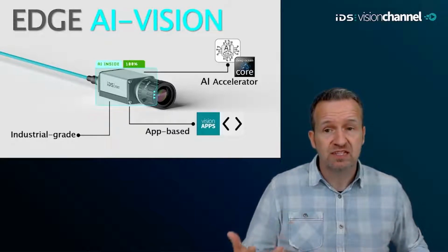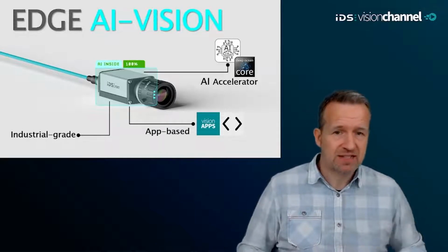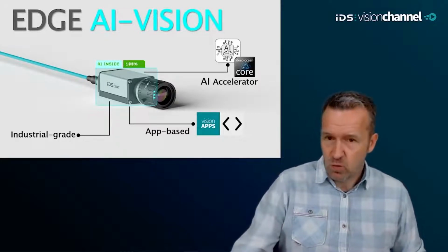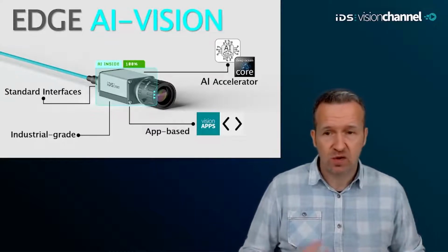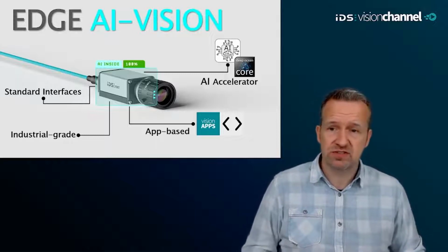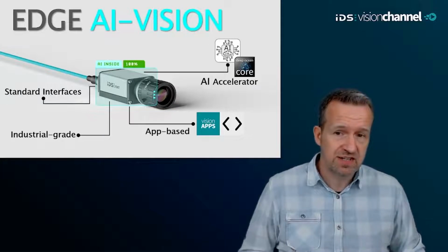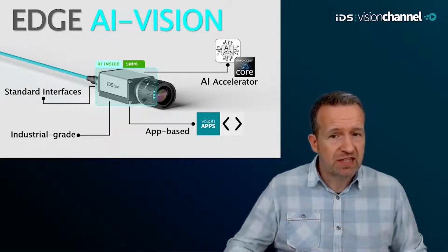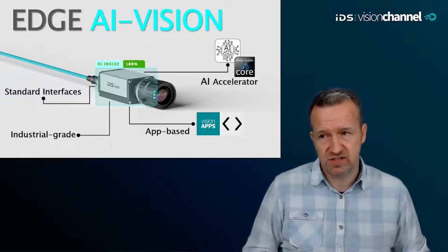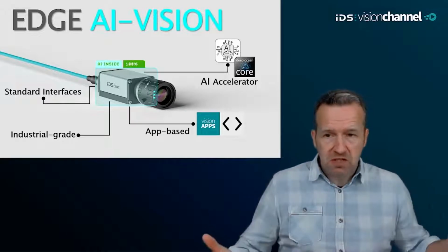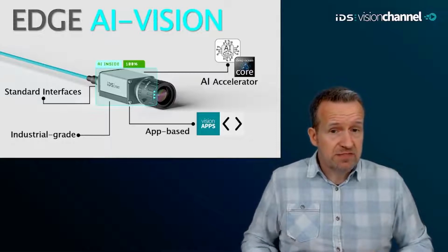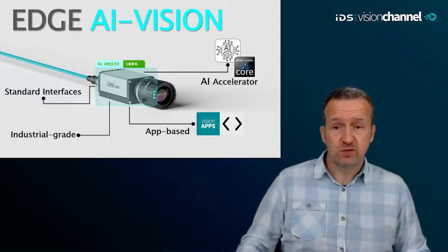Application processes are realized via vision apps, which can be exchanged quickly and easily, similar to a smartphone, and via standardized interfaces such as IOs, serial connections, Ethernet, and software-based protocols such as REST, OPC UA, or even a customized one. The cameras communicate, for example, inference results to PCs, PLCs, and other external devices or machines. All in all, they are intelligent cameras, as there are already several others on the market. But what makes our system different from the others?